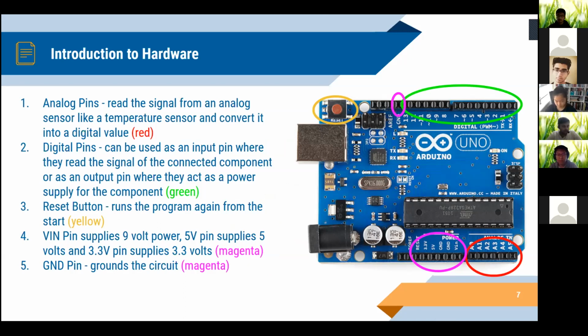either on or off. These pins can also generate a two-state signal, either at 0 or 5 volts, which is the logic of the Arduino board. They can also simulate voltages between 0 and 5 volts using a technique called pulse width modulation, or PWM, which we'll explore later. But there is no true way to generate actual voltages between 0 and 5 volts on the Arduino board. It will only be a simulation.